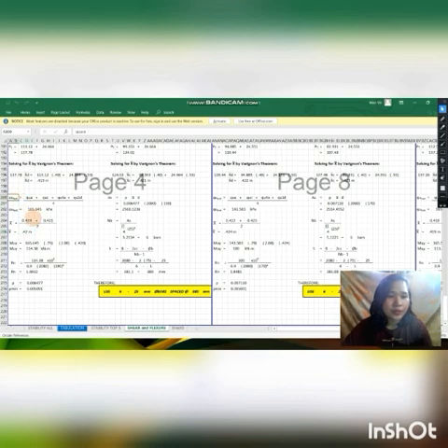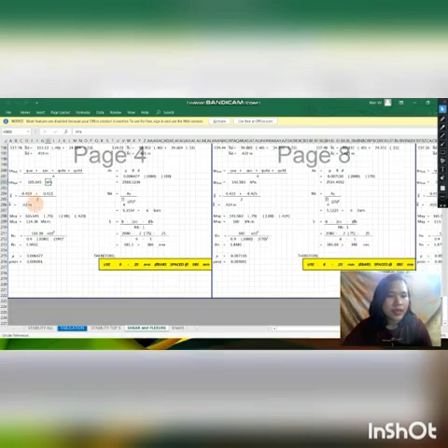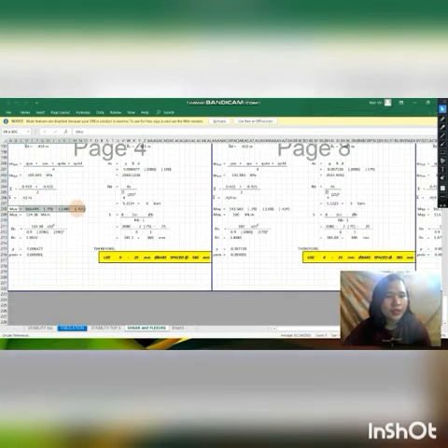So we will also get our QU average: QUA plus QUC plus QU4A plus QU4D, which gives 165.645 kPa. And substituting these values into this formula to get our MUY, we will have the answer of 114.38 kilonewton meter. So for our Rn, substituting MUY in our numerator times 10 to the 6th power so that it will give us an answer in MPa, all over the strength reduction factor of 0.9 times B times our depth, which is 190 millimeters squared, and the answer is 1.6922.